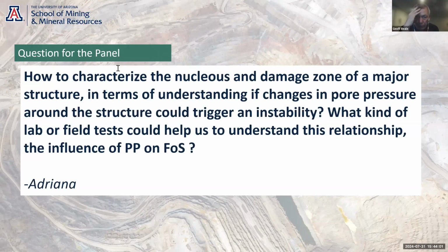Yeah, that's very true, Laura. And also important is the practicality. If it's a major structure, sometimes it may be difficult to put a piezometer right on the structure, but piezometers for sure, if you can put them on the different sides of the structure, and then you assess the orientation of the structure against the pit and see if there's any seepage, that can also give you an indication of the behavior if it's difficult to properly characterize the structure itself.